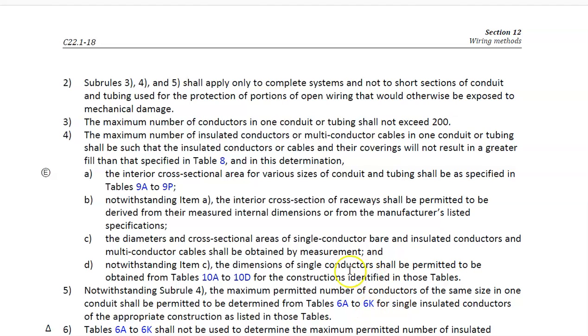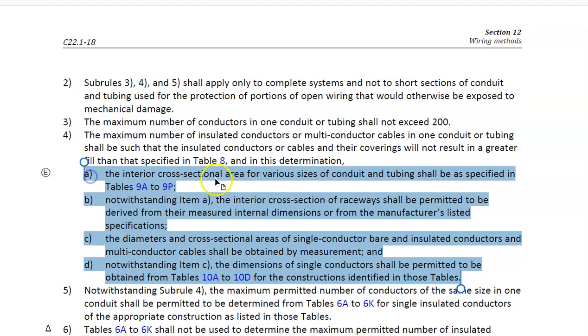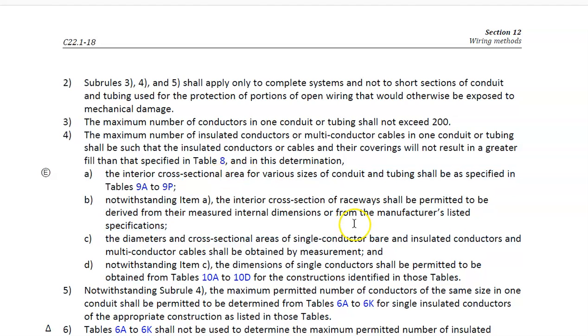If, however, I take the time and hand calculate it using these 4 over here, take my conduit area, take my conductor area, add them all together, and make sure that I don't go over 40% fill, there are actually some fairly substantial wins you can get. People might question, hey, isn't that overfull in a conduit? And you'd be surprised the number of times where you're not actually overfull when you do the longhand calculation.